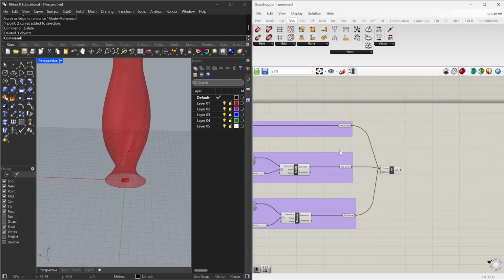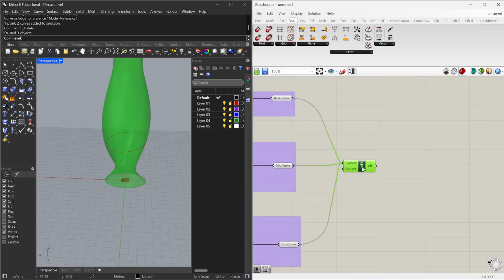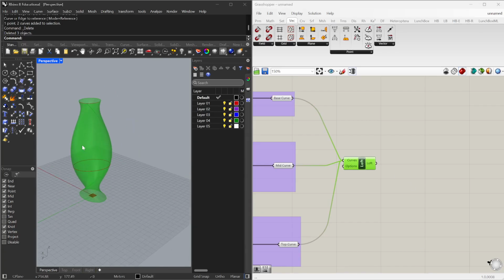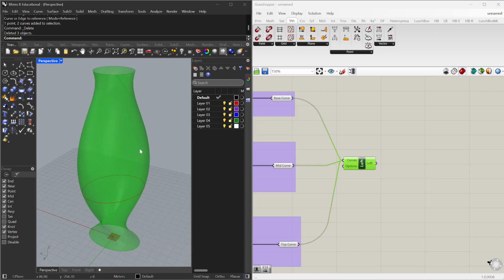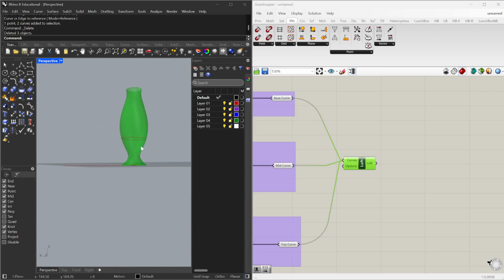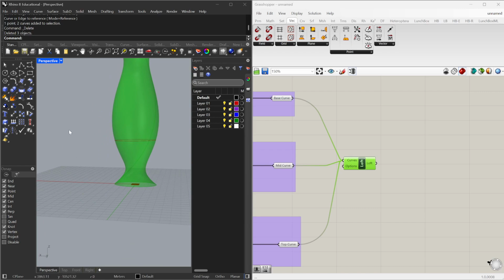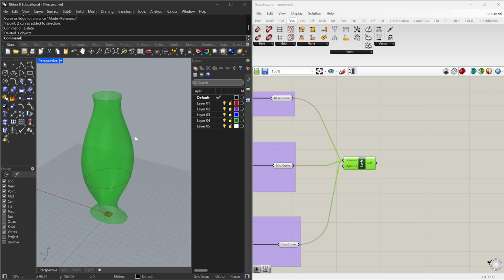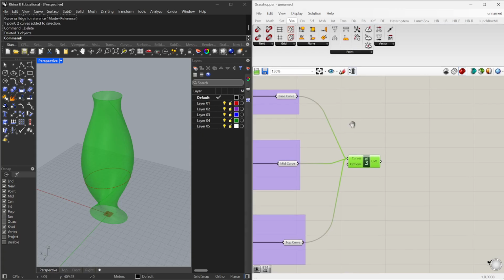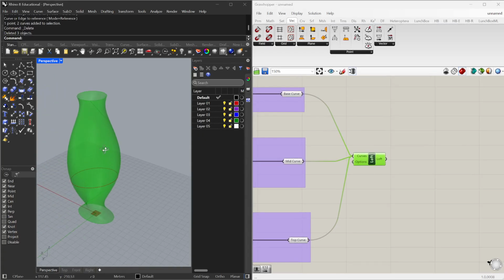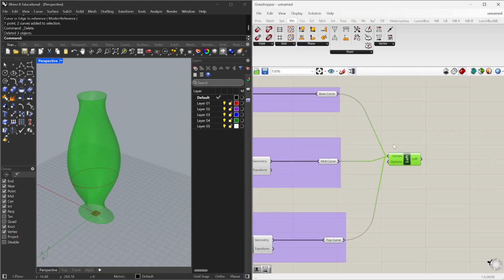Okay? So the next step that we're going to follow is, let's say we want to create some slabs in between here in our tower. In order for us to be able to do that, what I need to do is get some curves that go all the way up. And then I'll be able to use those curves to extrude it up and create some floor slabs, for example. So what I'm going to do to be able to do that is use a command called contour.